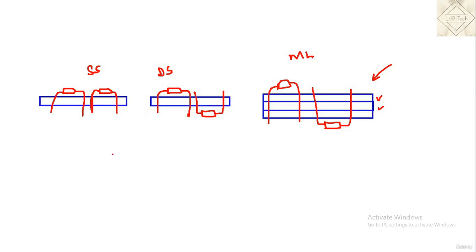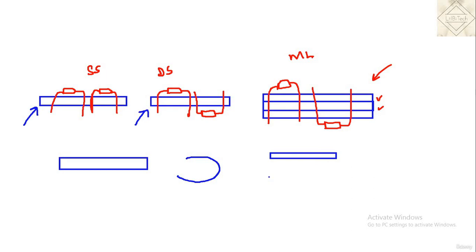Apart from this, we have the rigid flex PCB. These are the rigid PCBs if you consider it: if the PCB body is not bendable, all of that comes under rigid PCB. If you want to bend, it is used only for connection purposes, and that comes under a flex PCB. So if you want to connect different rigid PCBs using the flex PCB, we can use a rigid flex PCB.